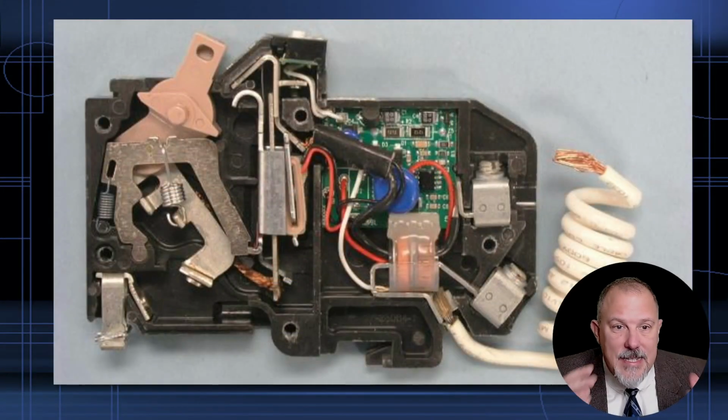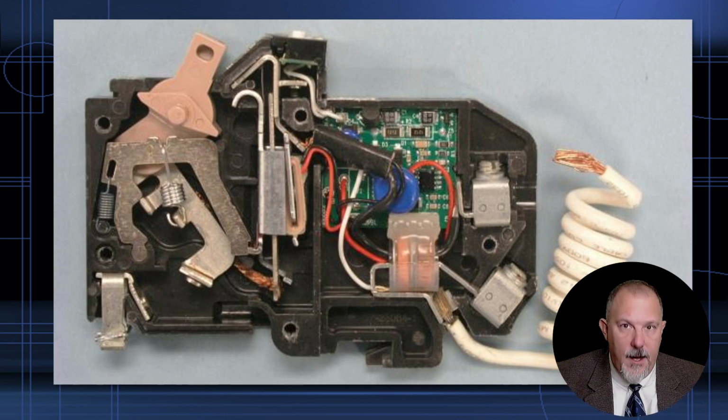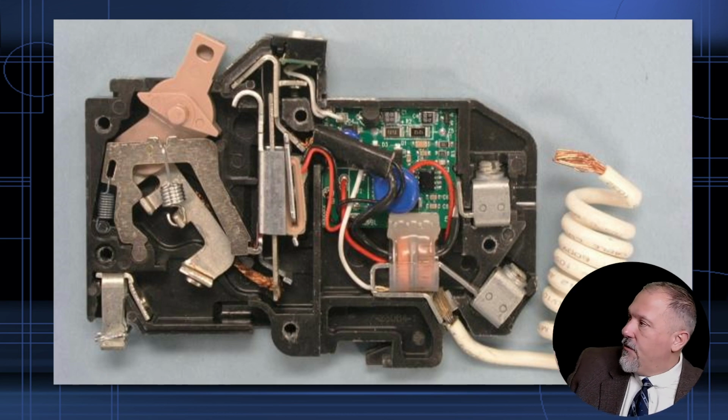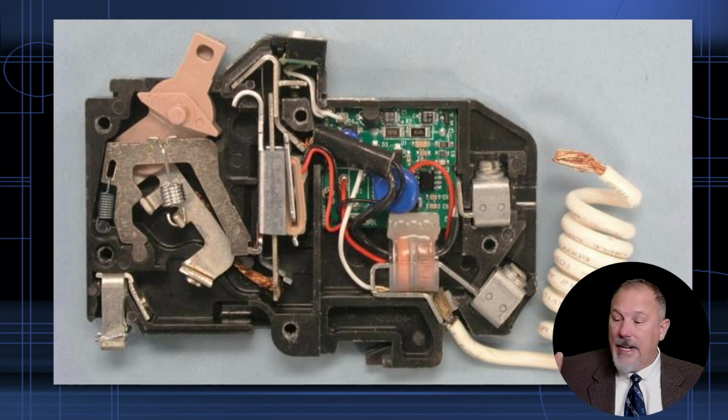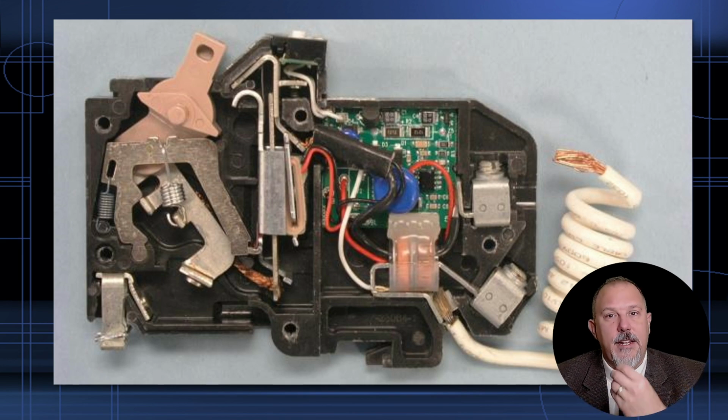Now, this is a close-up look at the internals of a circuit breaker. Furthest away from me on that end is what connects to the bus. Right here next to my head, the very top terminal is your hot, and the bottom terminal is your neutral. Remember, the GFCI circuit breaker is the only circuit breaker outside of an AFCI where you will terminate your hot and neutral conductors on the circuit breaker.